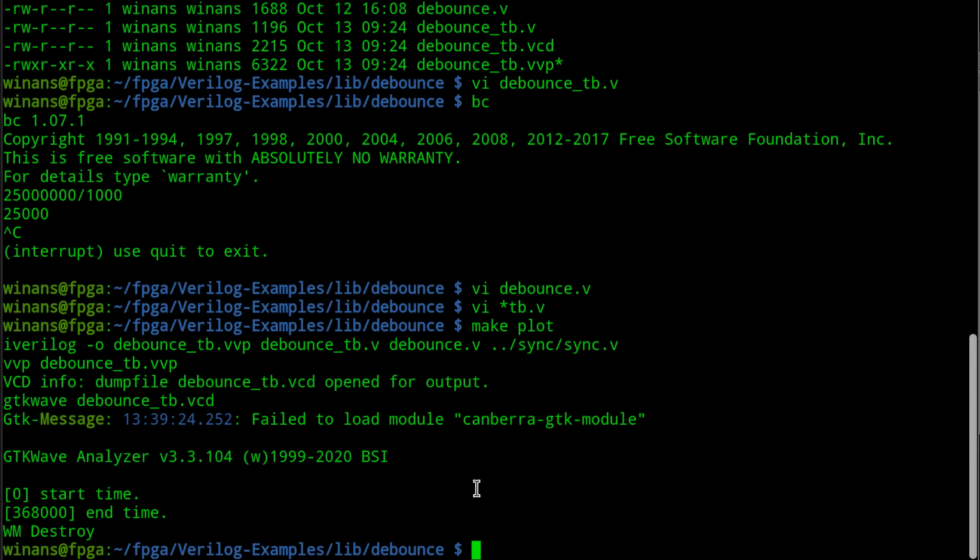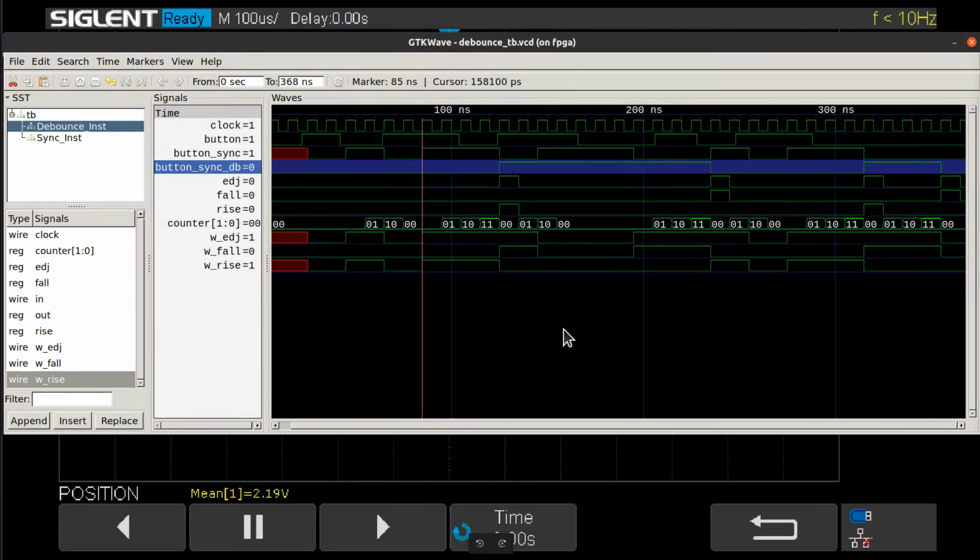And if you design a circuit that has more than one clock running in it, and that's not terribly uncommon, you get more of a sophisticated design going, you might have more than one clock running at the same time. And if you phase lock all these clocks, they can be considered in the same clock domain. In other words, as long as each one of the system clocks, when they change, they all go together, or they're adjusted accordingly so that they're out of phase in a way where they never can be in violation of the setup and hold time, then you're fine.